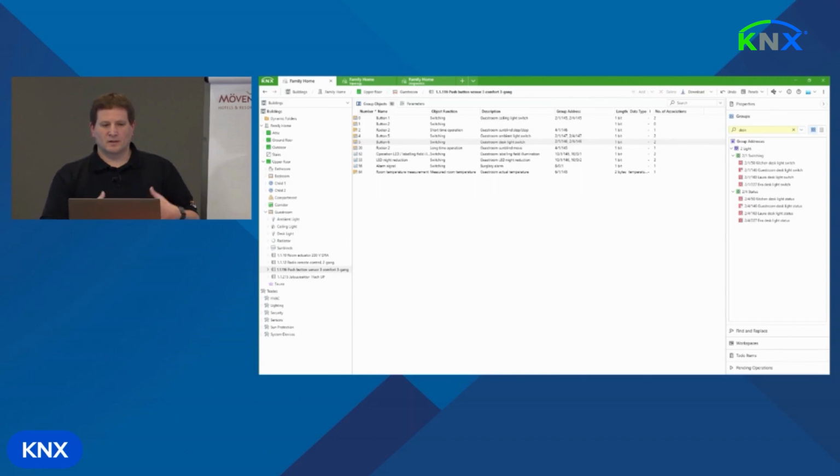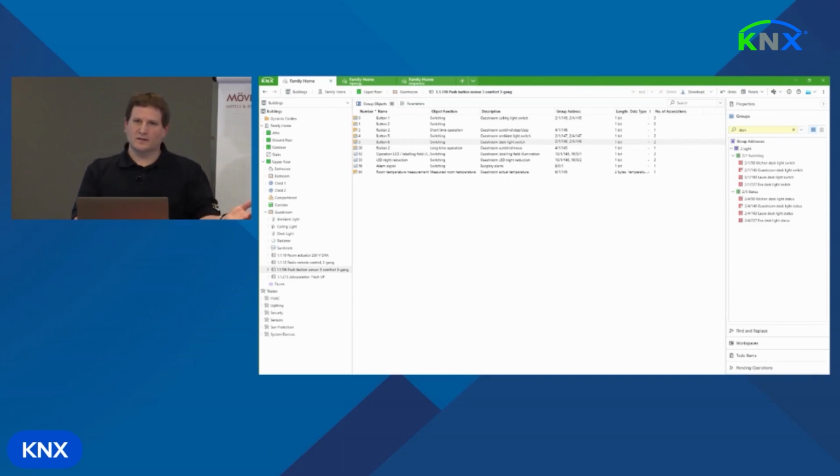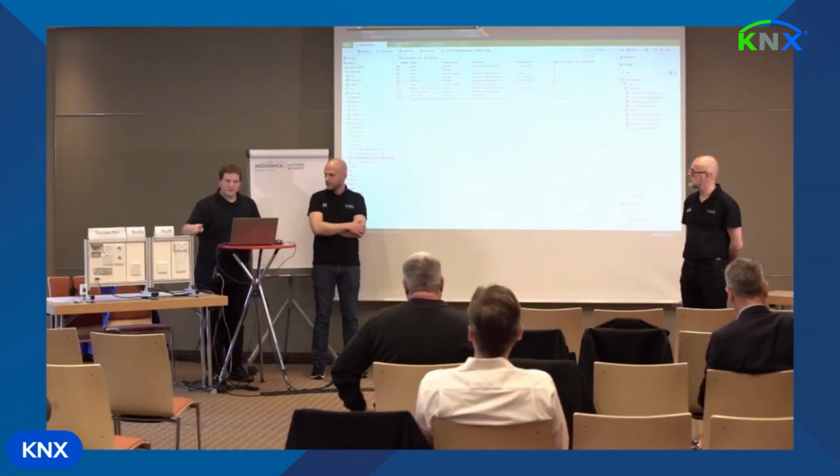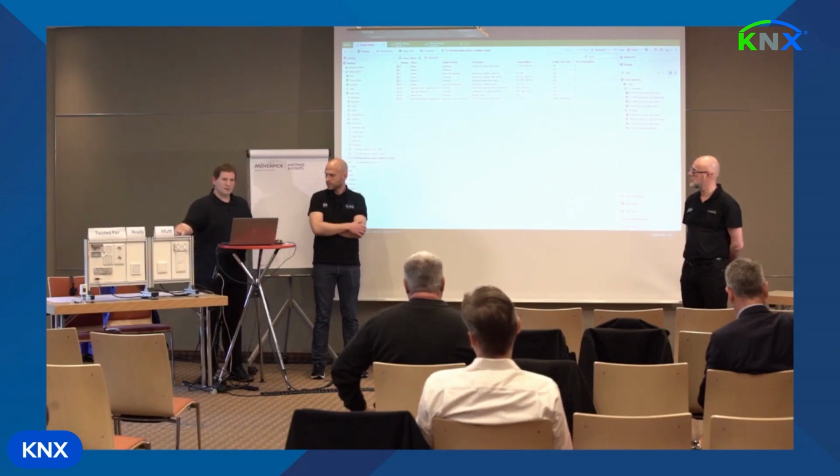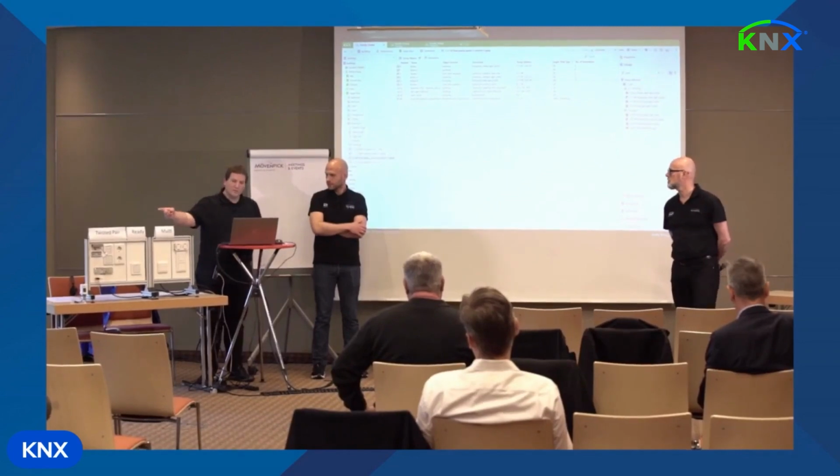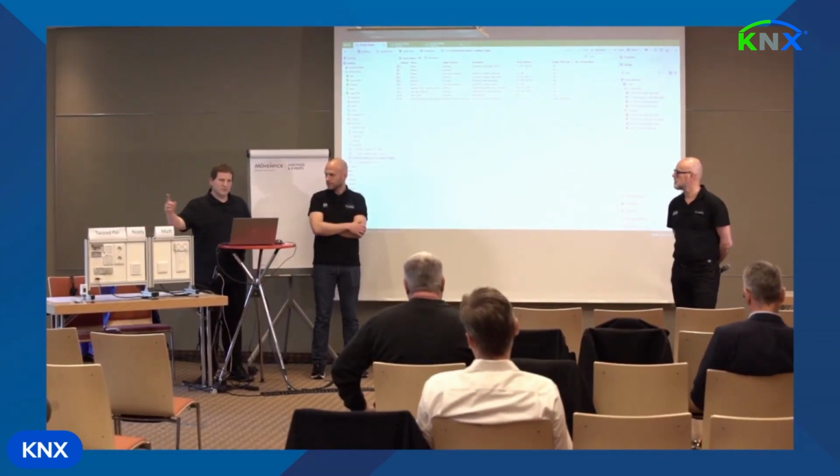For security, the receivers of a secure telegram need to know the list of trusted senders. So a visualization tool cannot simply send a secure telegram without being configured in ETS to be allowed as a trusted sender on this group address. And the same way we have this in RF with RF Multi. So ETS needs to know that there is a communication partner so that an acknowledge slot is reserved for this. We have seen this with this push button device, which at first only needed to communicate directly with the actuator. But when we added this group address in twisted pair, there was another communication partner stepping in, and this was the coupler. So the same frame then needed to be acknowledged by two recipients.